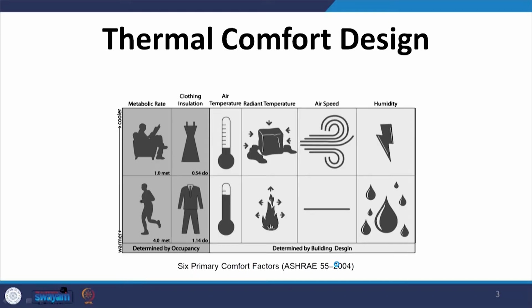One option is the prescriptive approach. If we are not doing that, the other way is to demonstrate this performance by using the local standard also. So, instead of ASHRAE 55, we could use an equivalent local standard. For example, in our case also we go back to ASHRAE standard 55, so for us it does not make much of a difference. However, in several other countries, especially in Europe, where they have their own thermal comfort requirements and standards, they may be used.